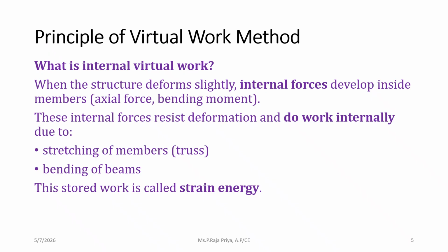So the same thing, whenever there is some deformation, some internal stresses or internal forces will be developed inside and they do the work internally. In case of truss, the deformation may happen due to stretching of the members. In case of beam, it will be due to bending. They store this energy, and that stored energy is called strain energy.